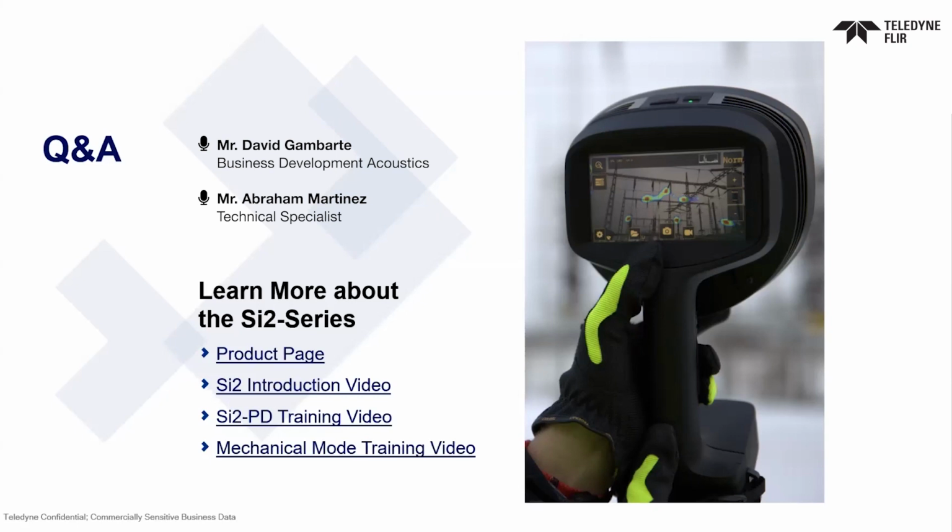Another question is, do we need to have inputs to the detected leak, such as distance, temperature, or humidity? I would say it's recommended to check the temperature and the humidity level before you start the inspection. Both might have some impact on the leak size calculation, so it might be relevant to check it in the morning or before you start. In many cases, you will not need to modify anything because the temperature might be similar over a certain time, but just check it.